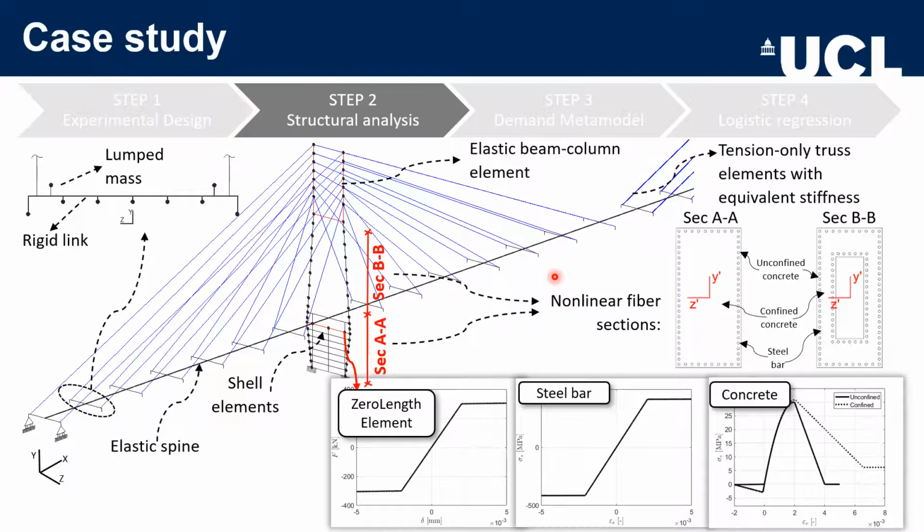My first question is, does it mean you haven't considered sagging in cables and cable strain? The second question is, are the rigid links free of rotation at the end? Because if not, I'm curious about its effect on horizontal displacement due to lateral load of the deck. And the last question, are the cables pretensioned?